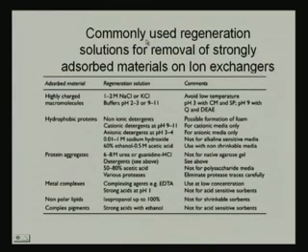Now, when we talk about the commonly used regeneration of these ion exchangers, some of the adsorbed materials are highly charged macromolecules, some are hydrophobic proteins, some are protein aggregates, metal complexes, non-polar lipids, complex pigments, etc. Different strategies of regeneration solution can be adopted, the commonly used regeneration solution for removal of strongly adsorbed materials on the ion exchanger matrix.